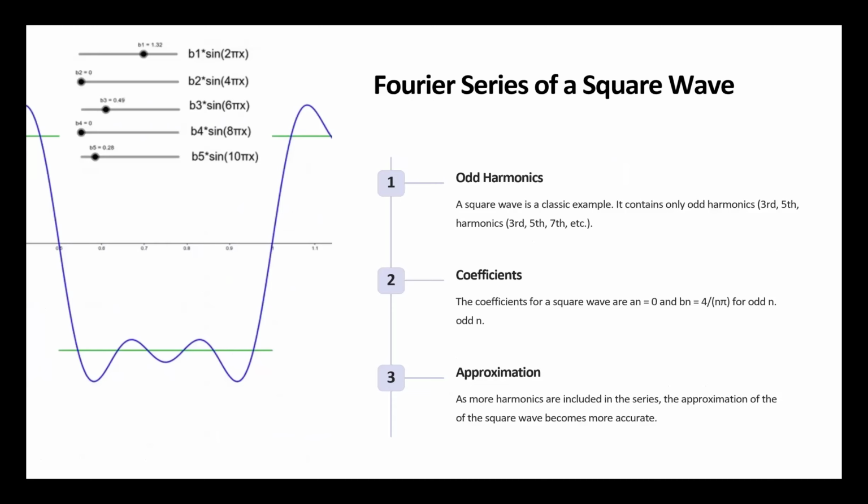Good? One good thing about pulses or square waves is that when you look at the square wave's Fourier series, they have very good characteristics. One characteristic is that all the harmonics that exist in the Fourier series of a square wave are odd multiples of the frequency.